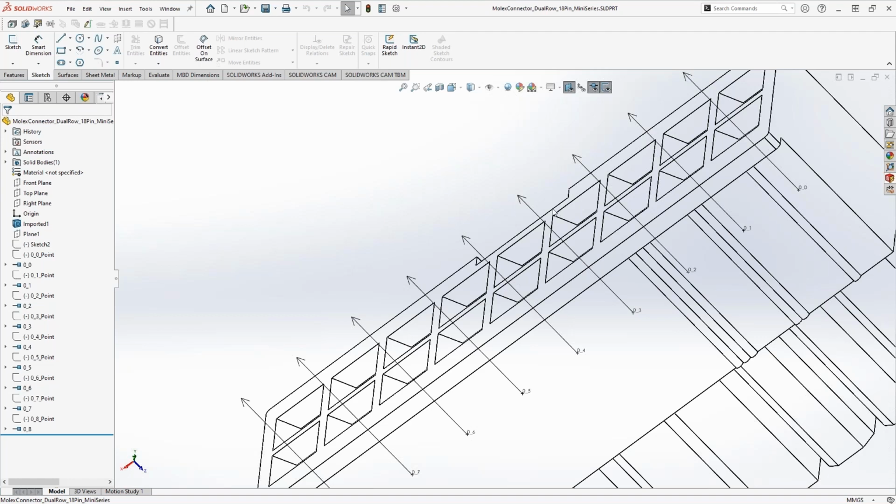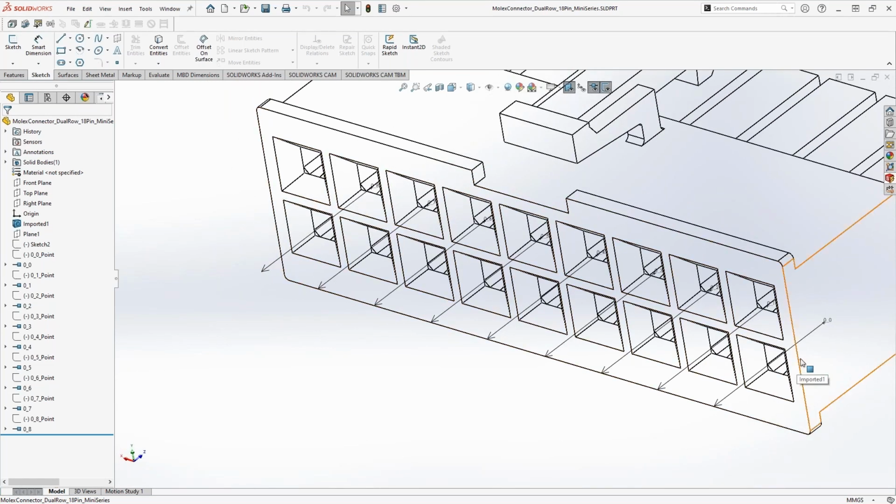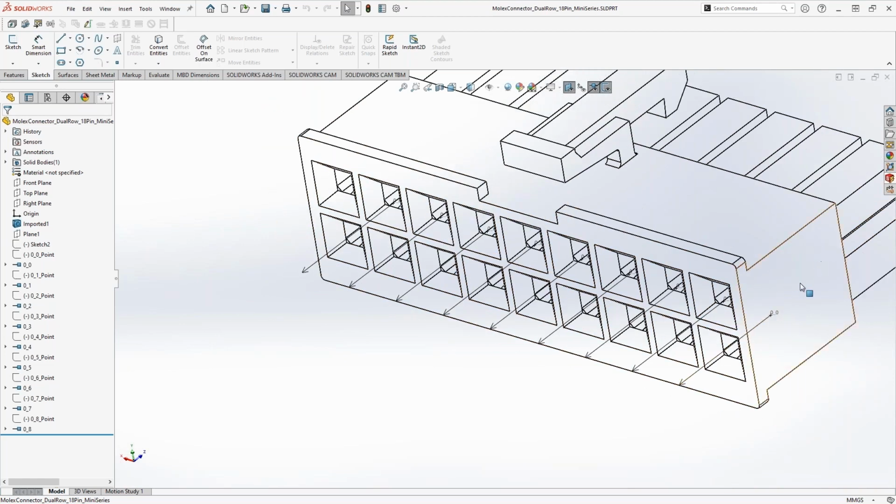And for those, not to get into teaching mode, but I like to do that every once in a while, right? In reality, where is that wire going to be? Is it going to go right to the face of this? No, that wire is going to be inside of a pin, crimped inside of a pin all the way down here. So in reality, I probably should have put those pins down here, which will give me almost an exact measurement and a length, which we will capture later on, of those wires from point A to point B.